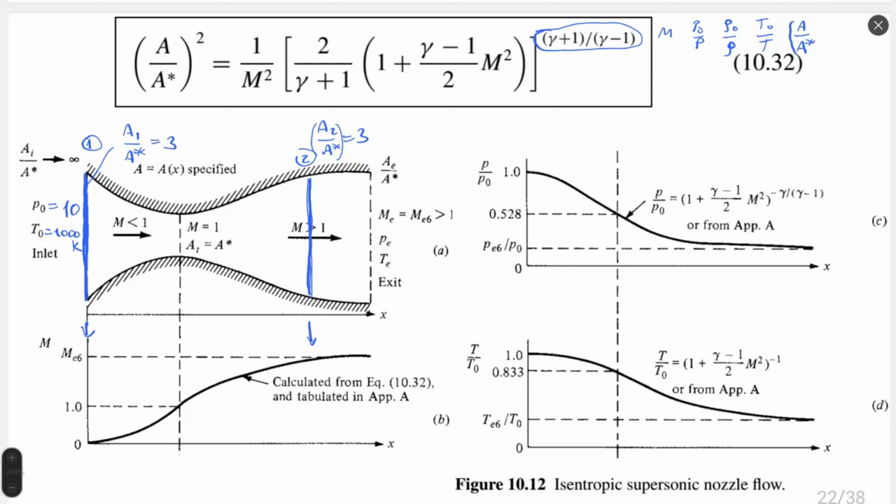So I will look at my nozzle area ratio, and I will search for a subsonic section. It's first part of table, and I will search for 3. Okay, where is it? It's somewhere on the first page. I will choose approximate value because it's not exactly equal 3. So I will see 3 on the subsonic section.